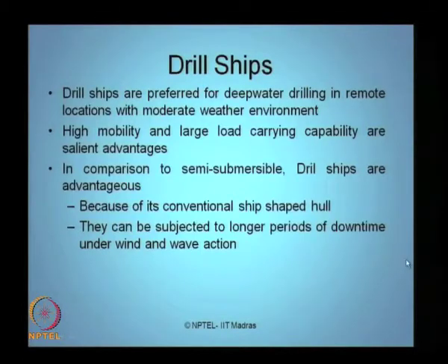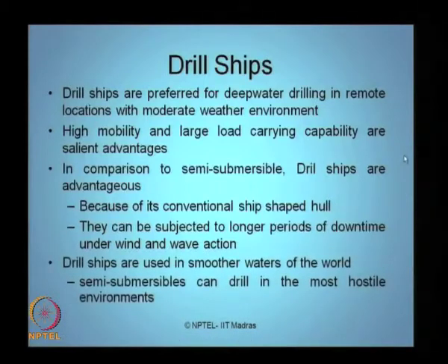Drill ships essentially can be used for smoother waters because I do not want a rough turbulent weather. Though you may wonder that in turbulent weather the dynamic positioning system will enable the drill ships to stay in position, performing a drilling operation in a rough critical sea state will always cause stability problems to the ship as such.